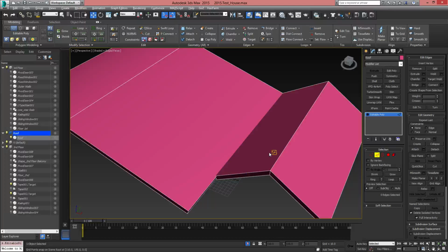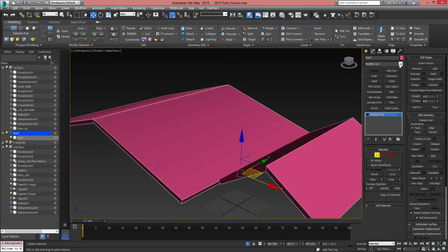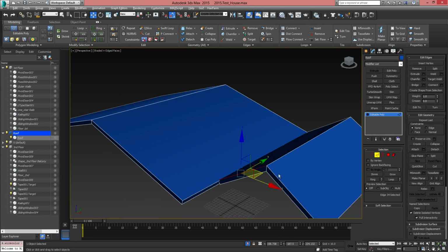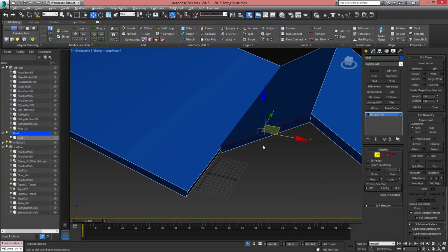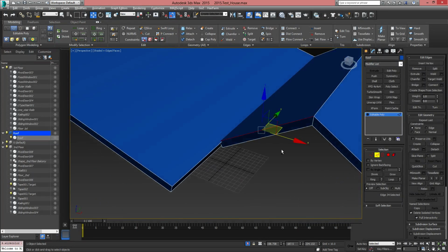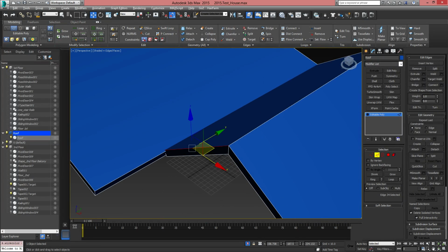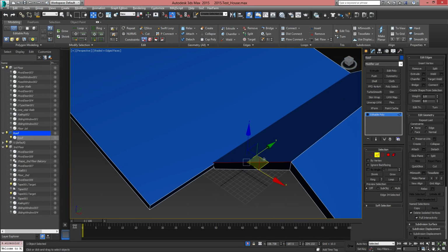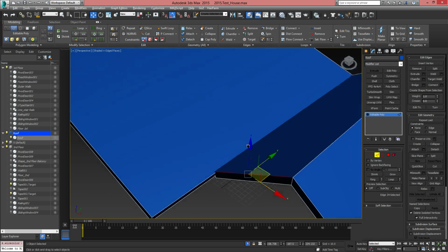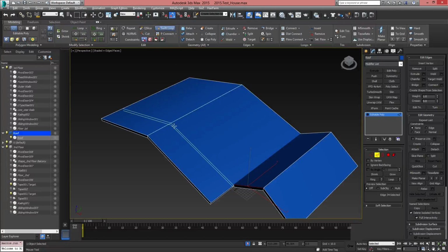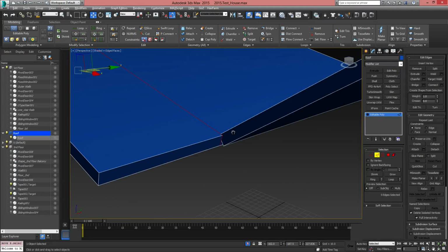Now I want to put a line going through this and turn off my snap tools. I'm going to change the color to something else so it's easier to see. Now I need to figure out where certain things are. So negative 87.5 is the location of this point here on the Y-axis for this line. So I want to draw another line that kind of matches up with that. So negative 187.5. So now that's aligned.